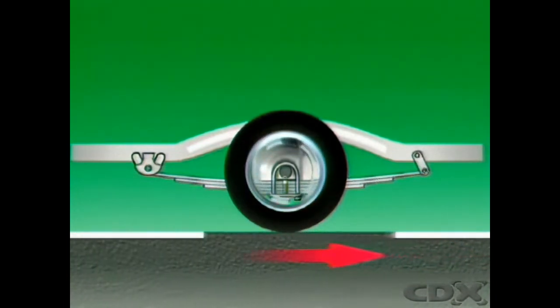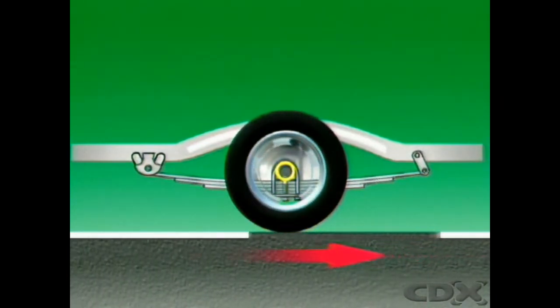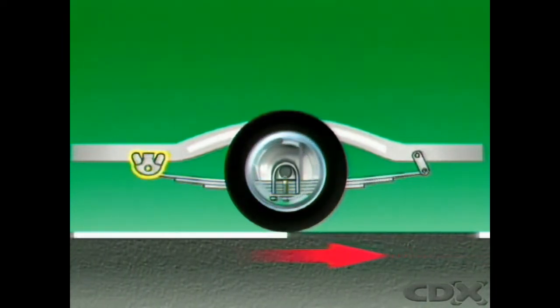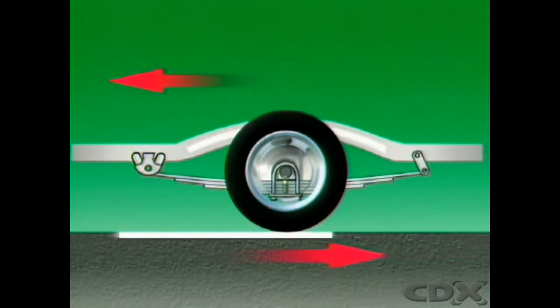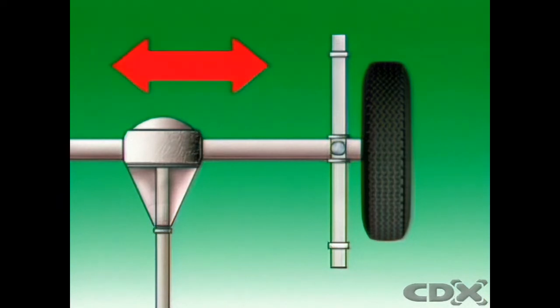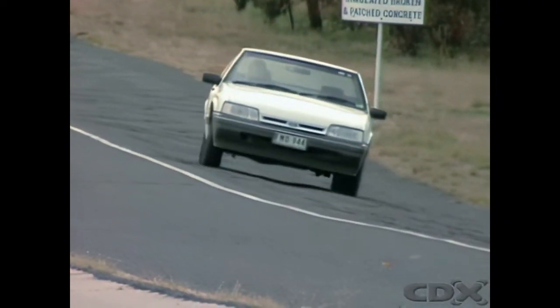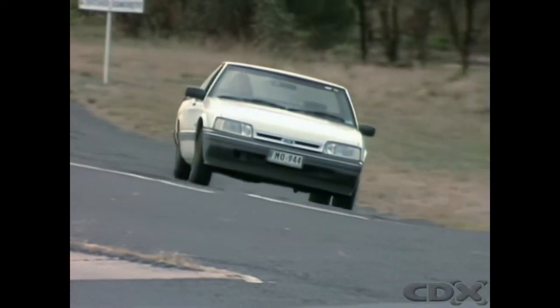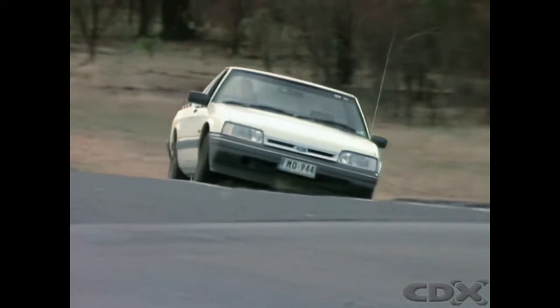Driving thrust is transferred from the tire contact patch through the axle housing and front half of the spring to the fixed shackle point. This pushes the vehicle along the road. During braking, the torque tries to twist the axle housing around its center, but it's held firmly, clamped to the spring, and any twisting effect is resisted by the relatively stiff spring. During cornering, lateral movement of the axle housing is prevented by its location on the spring center bolts and by the spring shackles.